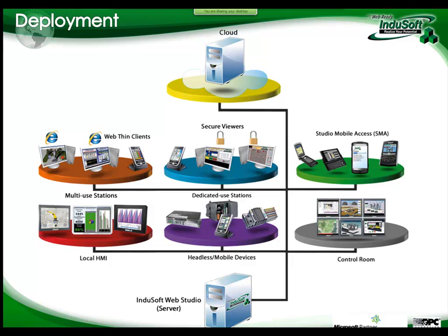Or you could have dedicated secure viewers. That would be our product called InduSoft Web Studio Secure Viewer, or InduSoft Secure Viewer. Thin clients that will basically be a remote visualization tool. So everything will be happening on one of these machines here, and you'll be seeing the screens, the alarms and the trending, all the history you will be retrieving using a remote viewer like this, okay?